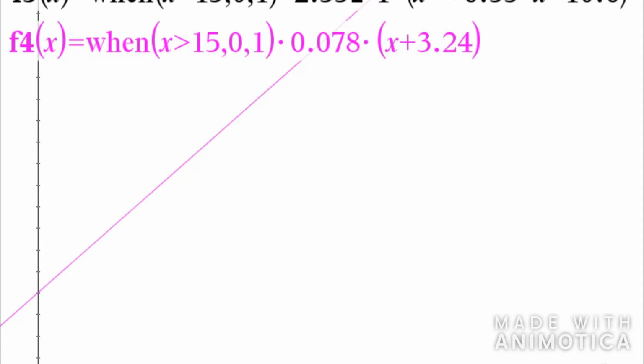And so from this graph we could look to pick off a particular point. Note that we cut it off at angles greater than 15 because in practice, really above 12 degrees, the fundamental theory this is based on, thin aerofoil theory, will begin to fail. That can be seen from other curves as well. But yeah, this is the most rewarding part, and this is what we'd hope students would gain the most from in this application.